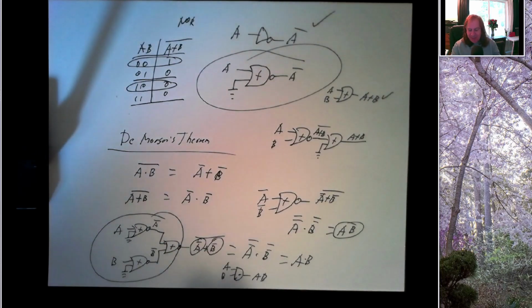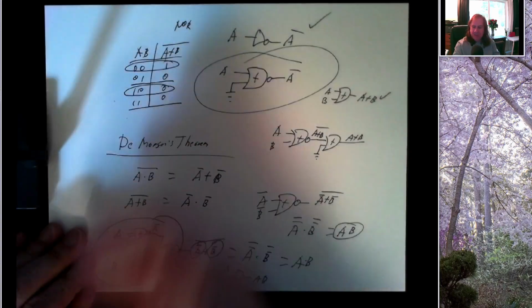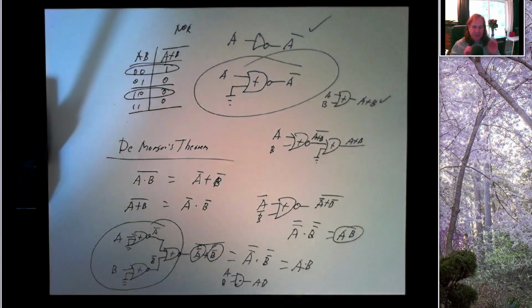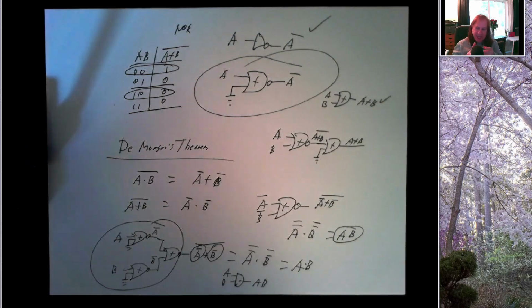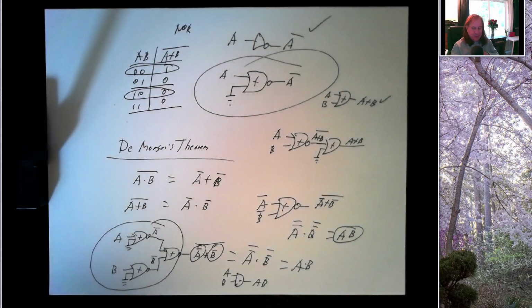And the same thing happens with NAND gates. If we start with a NAND gate, we can use NANDs to build NORs, ANDs, ORs, and NOTs. And it's kind of a dual process. The inverse comes from NANDing with a 1. And so we can redevelop this. So NANDs and NORs are universal building blocks. An AND is not. There's no way to get an inverse out of an AND, which means we can't get a NAND out of an AND. But NANDs and NORs, they're universal building blocks.